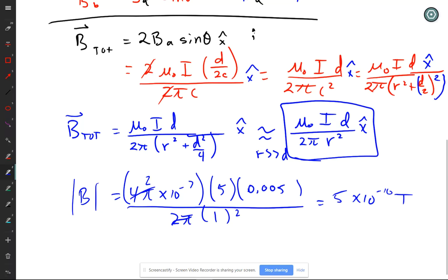A final thing, if you're running wire in your house: when I moved here to Lincoln, I put internet cabling throughout my house because it didn't have any. You want to make sure that where your internet cable crosses your power lines, they're perpendicular. Why perpendicular? Because then the magnetic fields aren't going to induce any currents. If you have them parallel, they'll induce currents. If they're perpendicular, they won't. So those are just fundamental rules for doing electrical wiring in a house to avoid having problems.